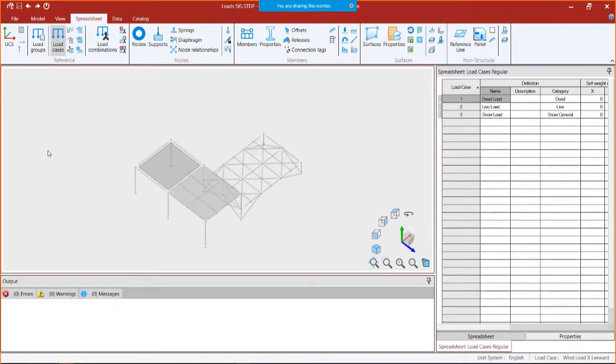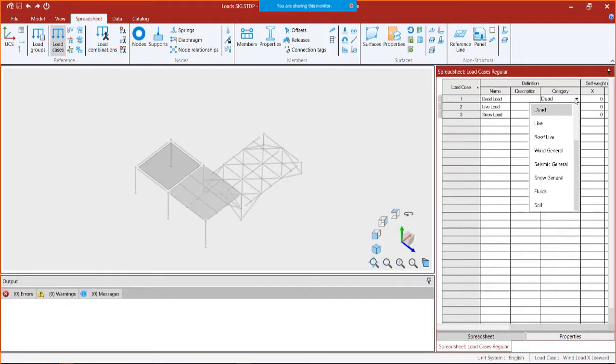As a courtesy, whenever you create a new physical model, they'll give you a load case, which I usually just rename to dead load. So that's what I did here. The program automatically gave me the first load case. I changed it to dead load and gave it a category of dead. As you can see, I can manipulate things directly through the spreadsheet, or I can use the tools within the ribbon toolbar. Now the categories work the same way they would in the STAAD.Pro Analytical Modeler, where by setting the categories you will be able to include this in load combinations later on.